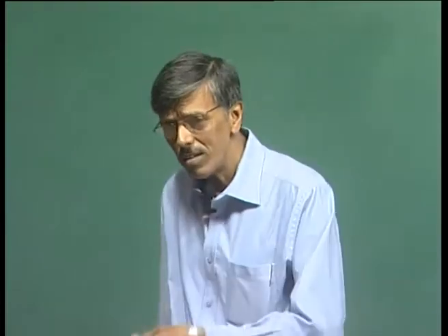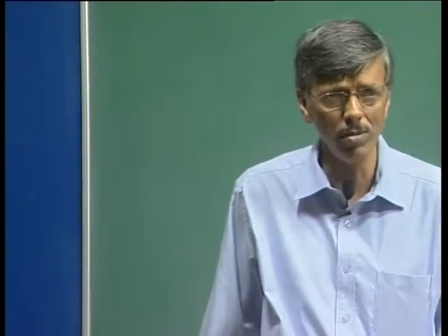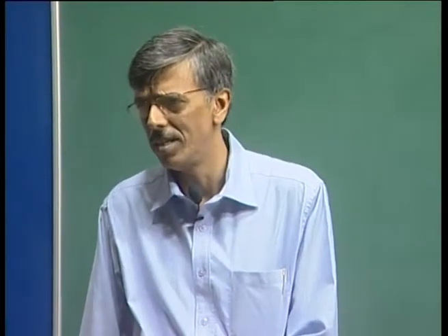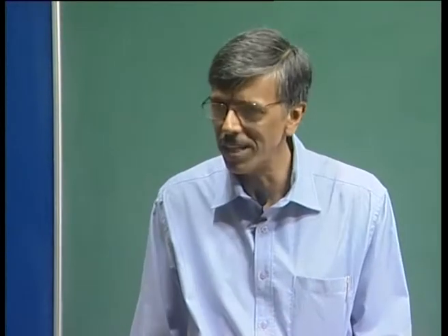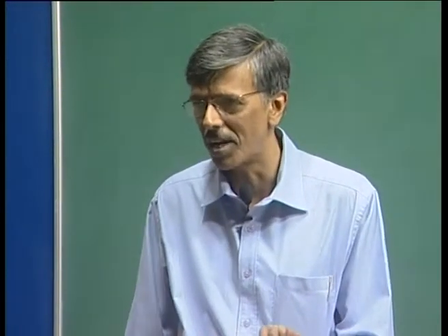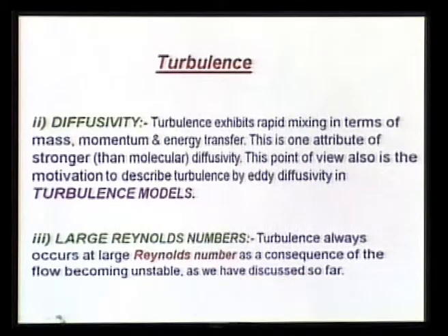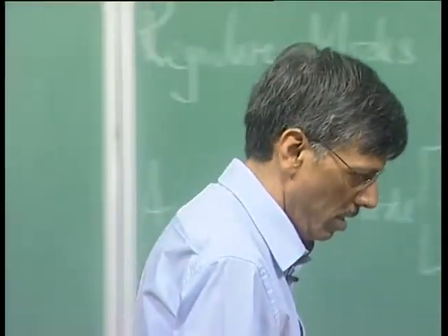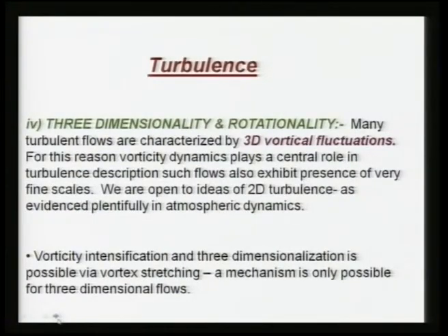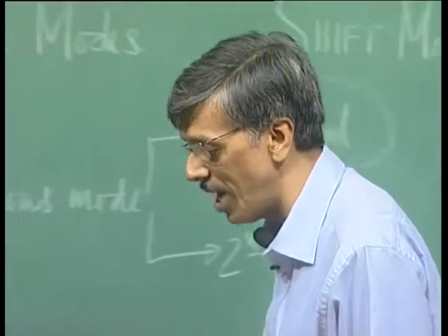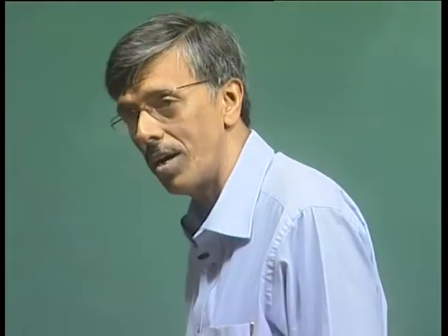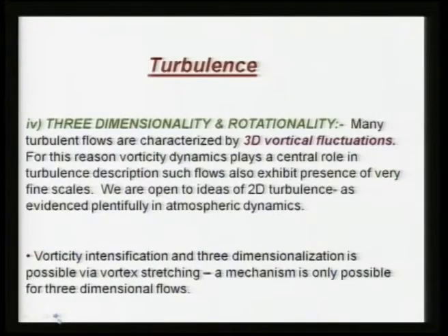But if I go to higher Reynolds number flows which are unstable, then once I get it started, it will be there, or I do not have to get it started. The small background disturbances are good enough to trigger it, right. So, this is something that we understand, that large Reynolds number is a necessary condition, not a sufficient one to tell you that all large Reynolds number flow will have to be turbulent flow. But the propensity of setting up turbulence is very much there when the Reynolds numbers are high. There is the other aspect of turbulence that we must keep in mind.